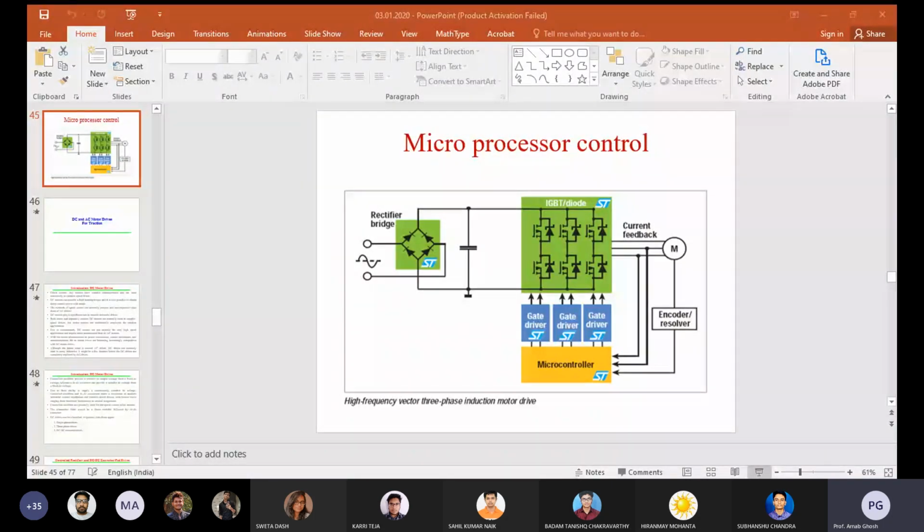And in very drastic environments there is a high chance of shorting the commutator segments. In between them there is some grooving, so if moisture or dust is deposited in between, it will automatically be shorted, and that can affect your commutator segments.